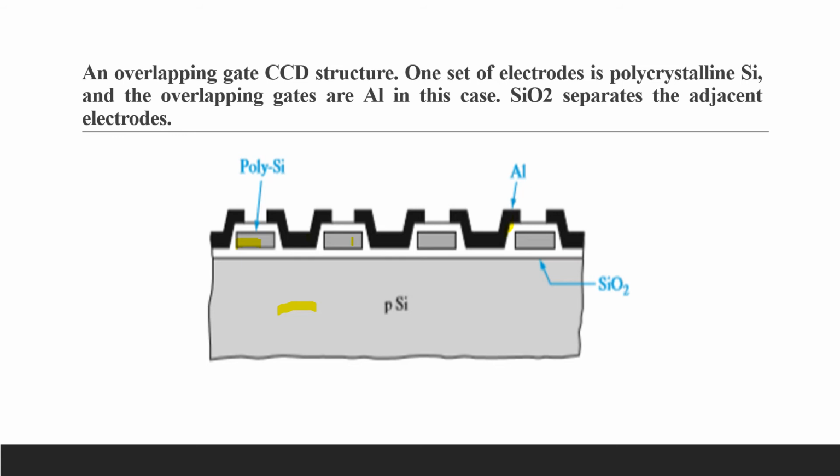One of the problems inherent to the charge transfer process is that some charge is lost during the many transfers along the CCD. If charges are stored at the silicon dioxide interface, surface states trap a certain amount of charge. Thus, if the zero logic condition is an empty well, the leading edge of a train of pulses is degraded by the loss of charge required in filling the traps which were empty in the zero condition.